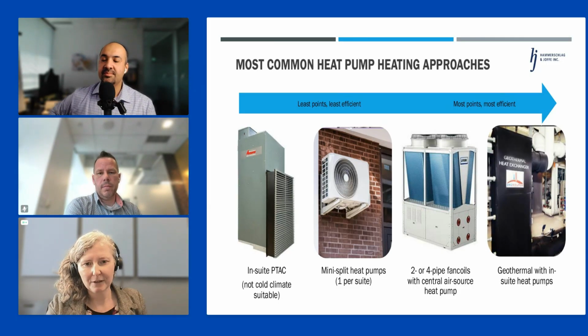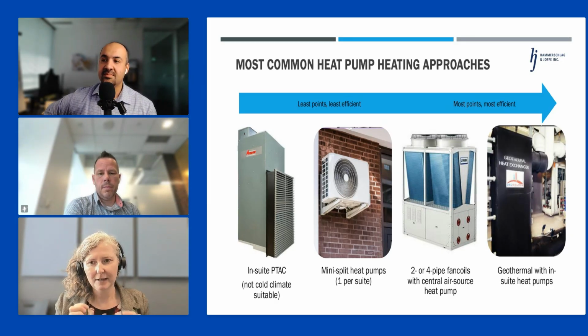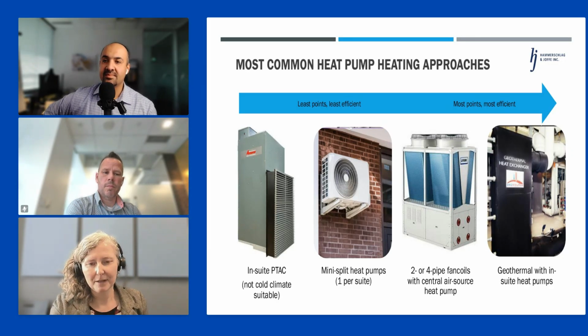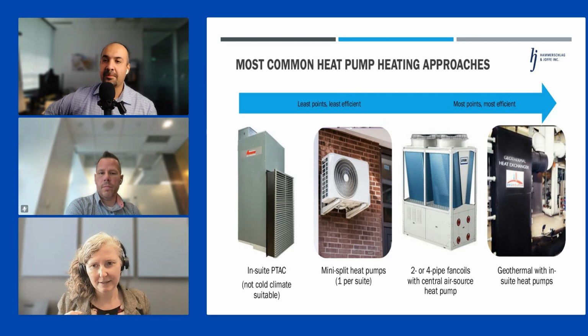We've been relying a lot on unitary packaged air to water heat pumps to limit the risks of that refrigerant transition for our clients, certainly this year, maybe next year. So this is a packaged piece of equipment because it's got a smaller and contained amount of refrigeration fluid inside of it. We're less worried about that transition.